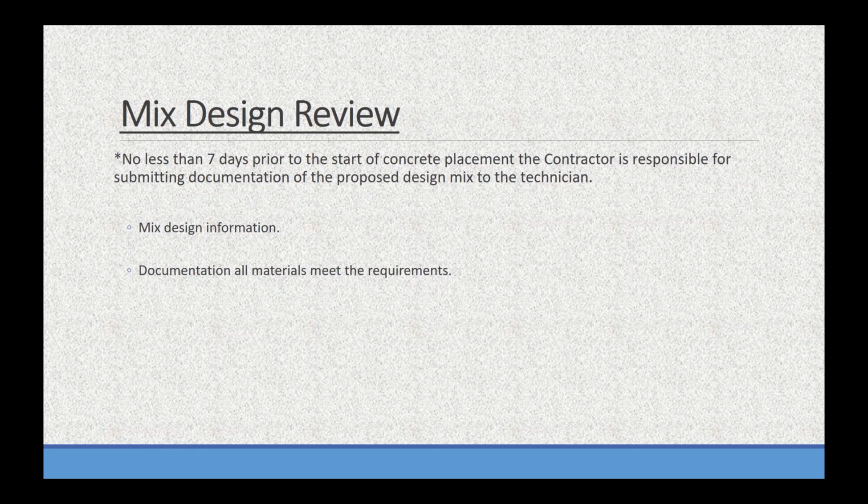Basically the standard says that no less than 7 days prior to the start of concrete placement, the contractor is responsible for submitting documentation of the proposed design mix to you, the technician. And basically what that entails is the mix design information, which is the second section of the presentation. Some of those percentages and things like that is what you would be checking for the mix design.